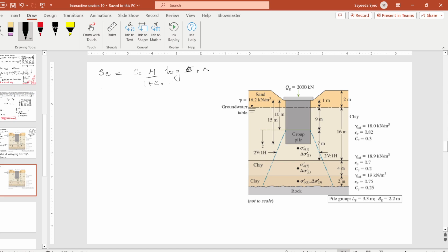As we had done for the shallow foundation, if the soil is overconsolidated, you take the swelling-shrinking coefficient, Cr, and for normally consolidated, we take Cc. We also talked about a case in which sigma is NC, but sigma plus delta sigma is OC. In the NC range, you will take Cc, and for sigma plus delta sigma, you will take Cr. So we have talked about this.